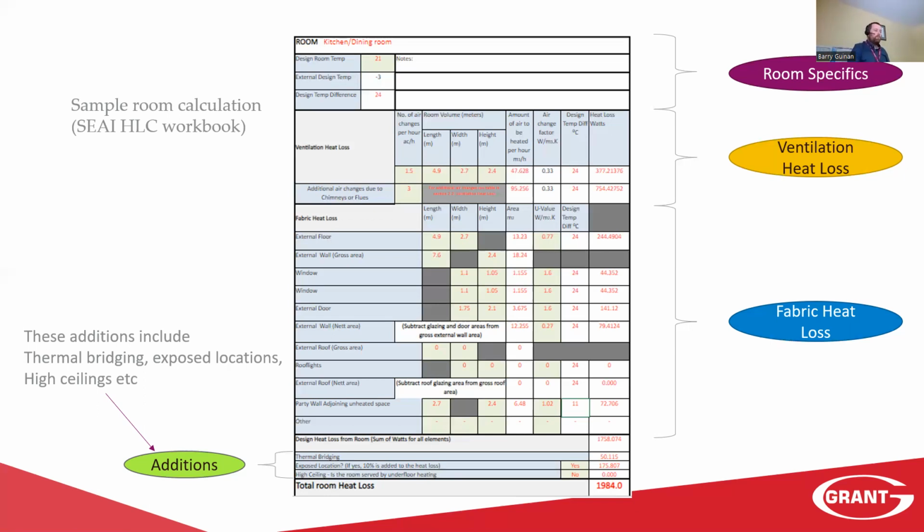But in order to use those lower values, you would need ACDs and signed drawings from the architects and the builders that the thermal bridging has been reduced. So in most cases, you would just take it at 0.15 unless you had the evidence to support it. You would also then possibly add in percentage uplifts for a building being in an exposed location.